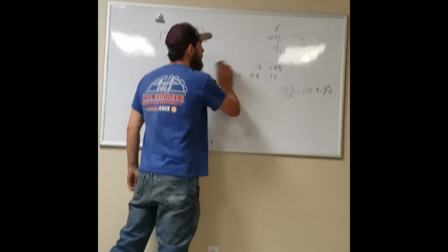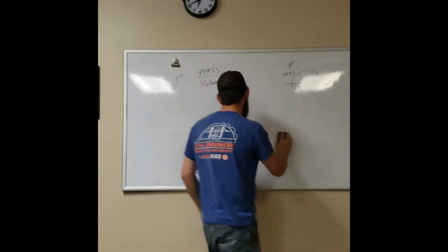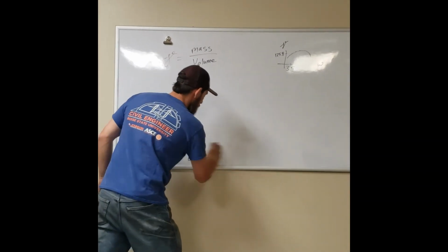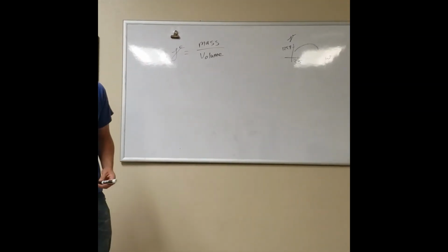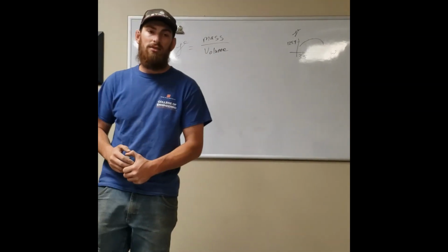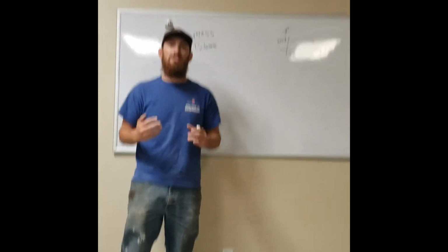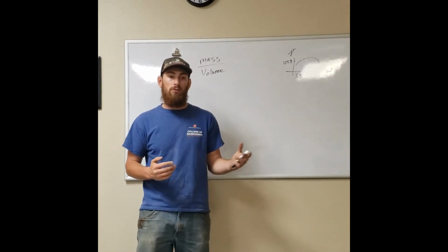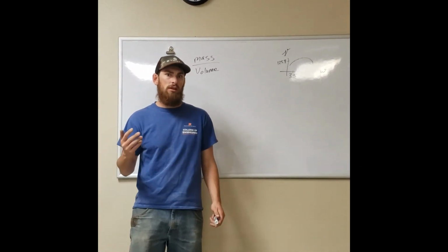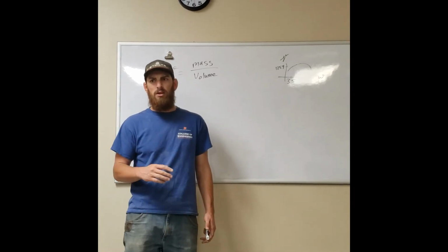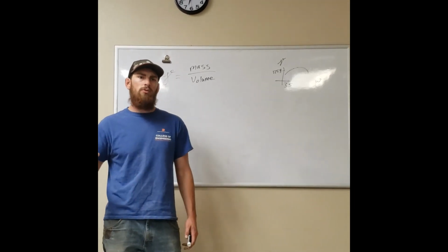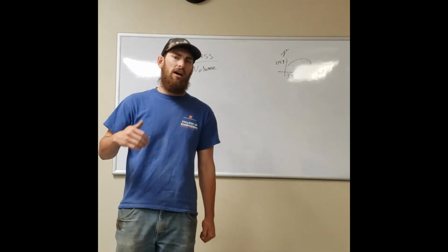Now the sand cone that's going to go with this is the field version. So what I'm getting is a theoretical maximum dry density, okay? So that's the densest it could possibly go. There's a couple different versions of doing it, which will give you different results. It's basically an old method and a new method. All the engineers out there like to use what's called the modified, because you get a higher value.